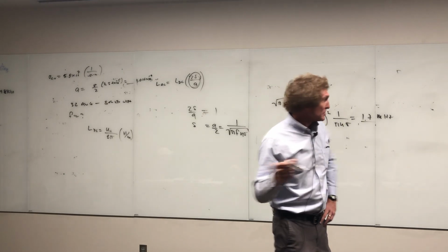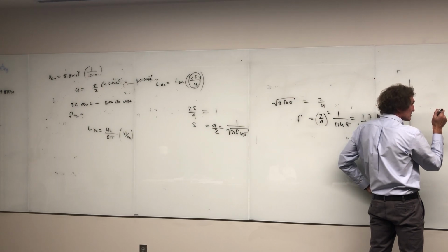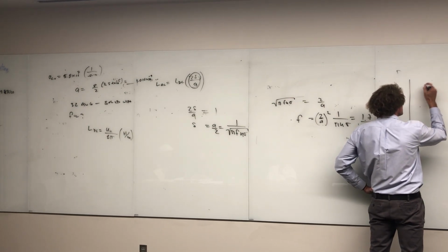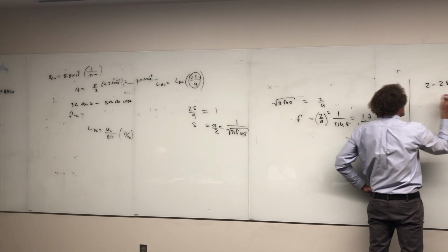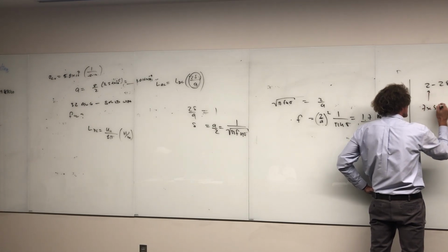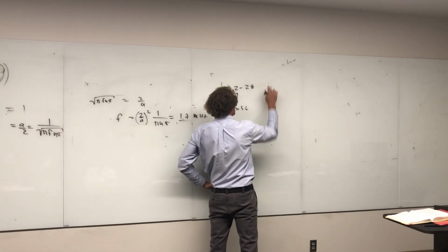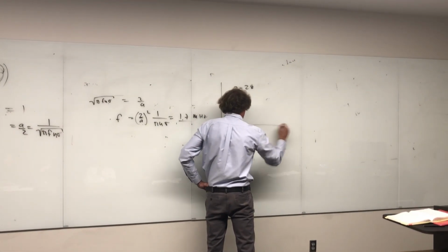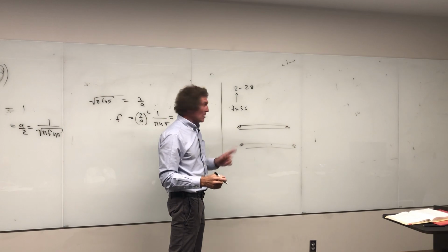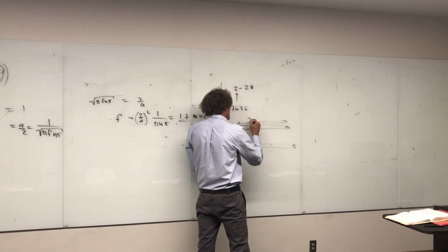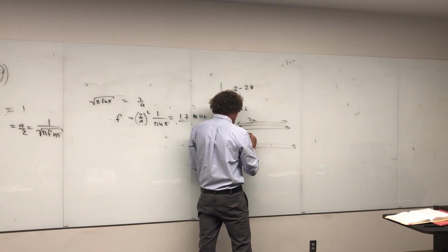Okay, this is a decent one. Determine the resistance, internal inductance, external inductance, and capacitance of a typical ribbon cable consisting of two 28-gauge 7 by 36 wires, 2 meters in length and separated by 50 mils at 100 megahertz. All right. This is going to get a little long, but what's the length on this thing? 2 meters. And separation distance? 50 mils.